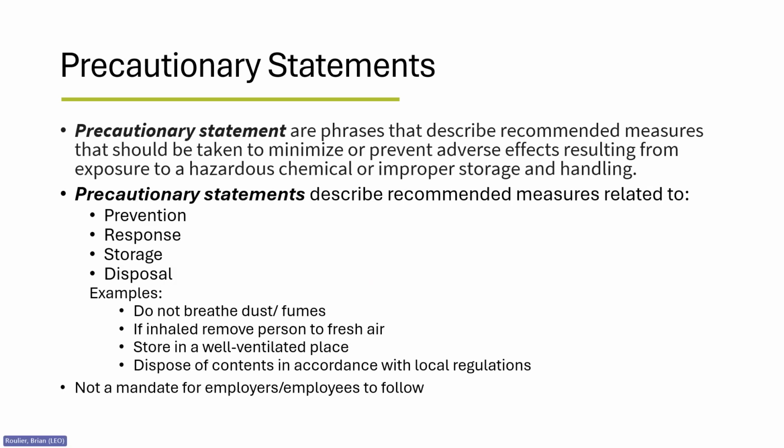Precautionary statements are phrases used to describe recommended measures to minimize or prevent adverse effects from exposure or improper storage and handling. These statements relate to preventing exposure, the response if exposed, storage, and disposal of a chemical. For example, these statements may include, do not breathe dust or fumes. If inhaled, remove person to fresh air, store in a well-ventilated place, dispose of contents in accordance with local regulations. Each facility's use, process, and exposure to a chemical may vary, and all precautionary statements may not apply in every situation.